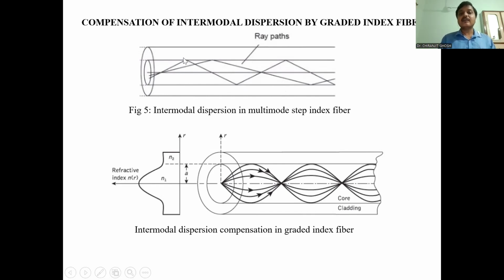And we all know that these are not mirrors. These reflections are formed by refractive index variation, total internal reflection, so they cannot reflect 100% of light. Maybe 90% of light will be reflected and 10% will go. Again here, 90% of 90% will be reflected, and 10% will travel in the cladding. So at each reflection, some light is always getting lost in the cladding.